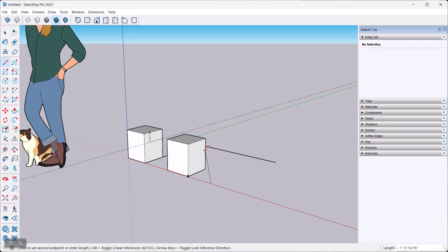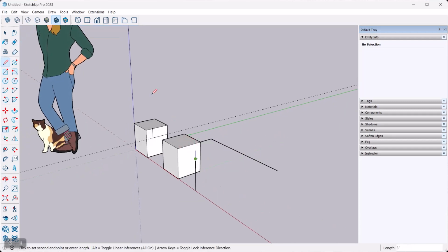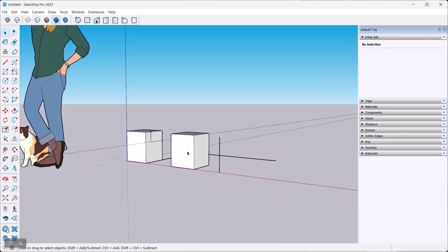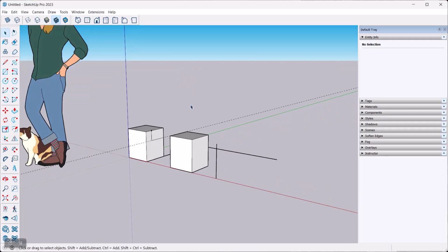So in other words, once you have some kind of a reference and you hold Shift, your mouse can do whatever it wants to. You'll stay on that reference. Once you let go of Shift, you're basically in 3D space again. So that is really useful in combination with everything else to just keep things straight. The same thing works with some of the tools, like the rotation tool, for example, which needs a plane about which it rotates. As you can see here, it'll guess something based on where your mouse is. But if you want to rotate something about a certain plane and you want to lock to that plane, independent of what you do, then of course your Shift key is again your friend. All right, so inferences, very nice. All right, next, selecting things.